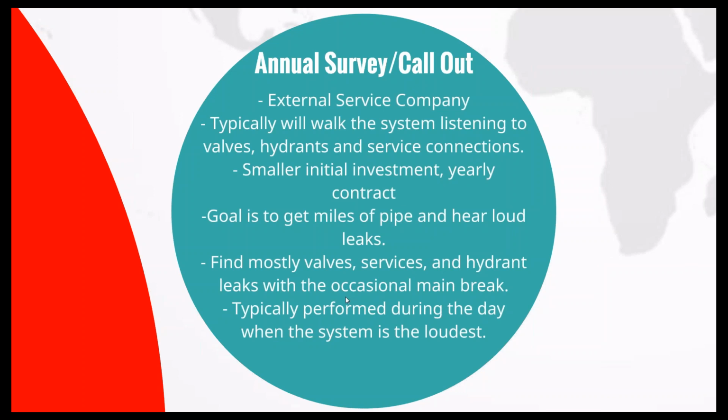And typically these are done during the day when the system is loudest, because during the day, usually in residential areas especially, the demand is lower, so the pressure will be higher. People are out working, so your pressure's higher, so those leaks will be more apparent during the day.